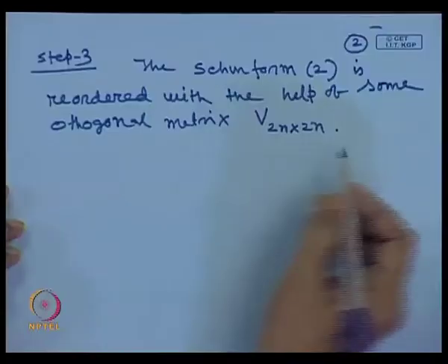Again on S we apply an orthogonal transformation so that S is converted into a special upper triangular form, with all the stable eigenvalues put first and the unstable eigenvalues next.